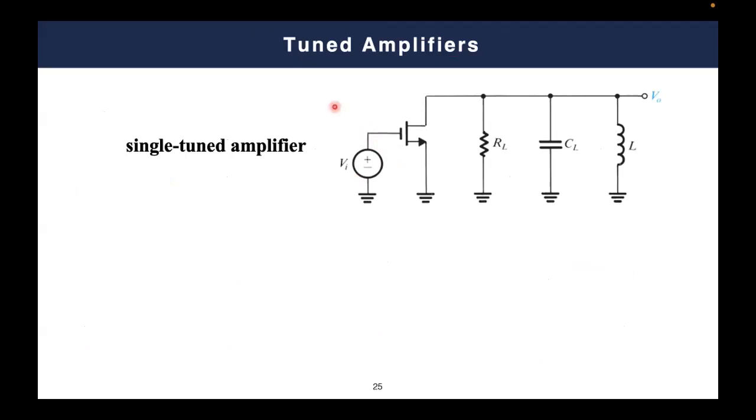Because if you have an input signal, which should be some sort of sinusoidal input, and this sinusoidal input is applied to the gate, for example, considering a threshold voltage for the MOSFET of about 1 volt or whatever, that basically means your MOSFET will only operate in this region. And whenever your input voltage is below the threshold, your MOSFET is basically off. So this is not a suitable amplifier.